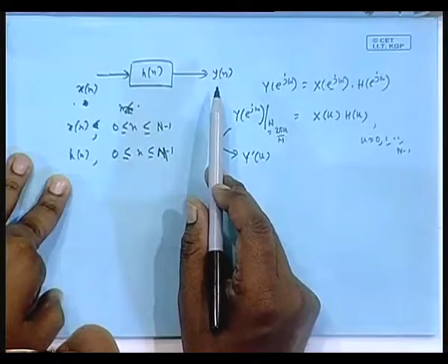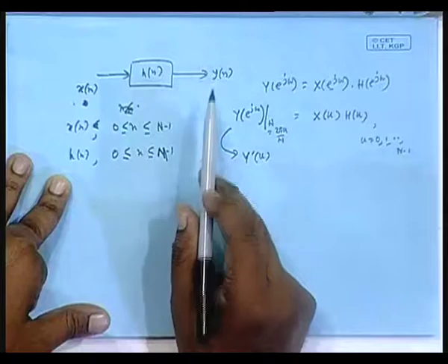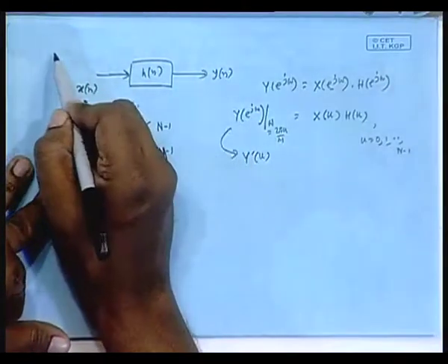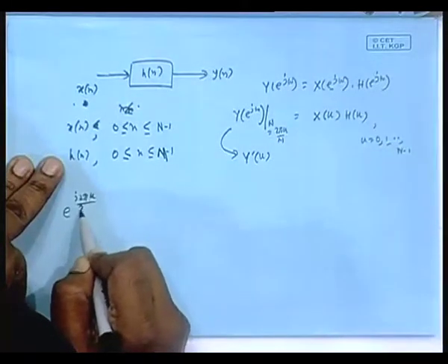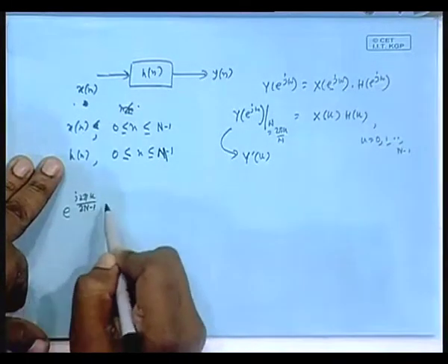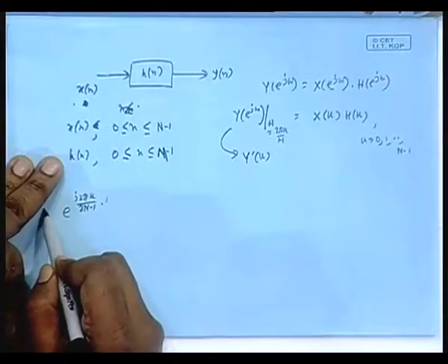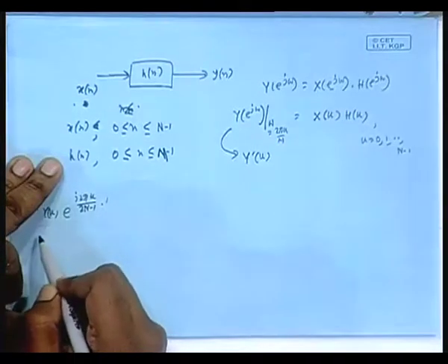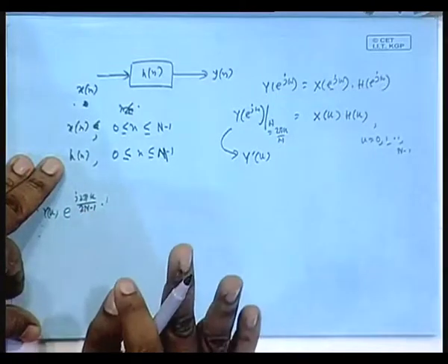Not n. 2n minus 1. So firstly, its DTFT should be sampled at least 2n minus 1 times, and there the basis function should have been e^(j2πk/(2n-1)), not n, times n, multiplied by the corresponding coefficients, Y[k] or whatever you say, and k will go from 0 to 2n minus 2, total is 2n minus 1, then it is okay.